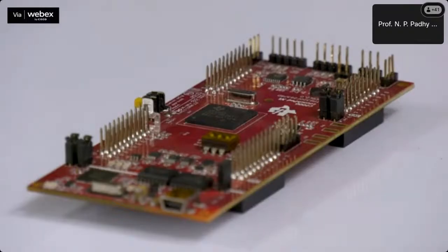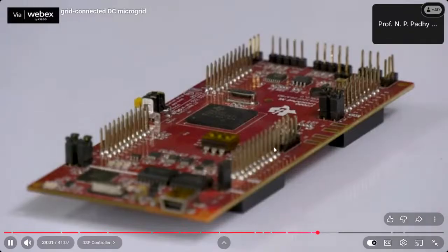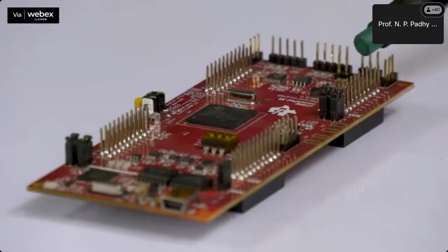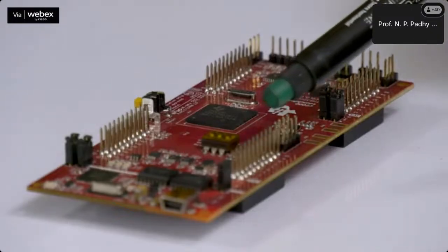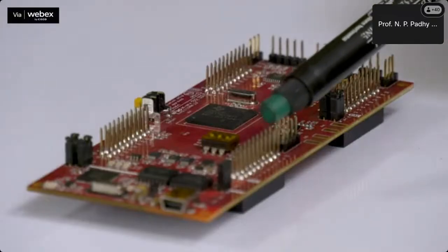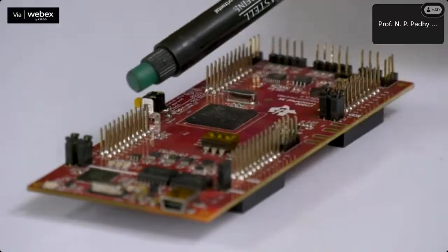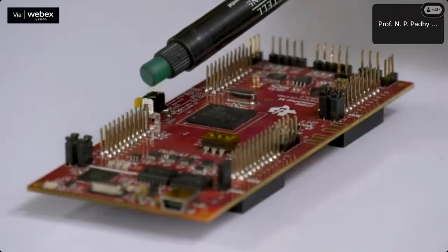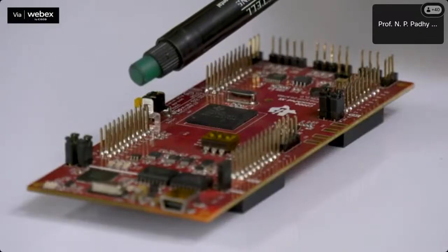The DSP controller is the most economical controller that is used for grid integration applications. For developing any rapid control prototyping, we need to configure the analog to digital converter, ADC, and PWM pins of the DSP controller. Generally, the DSP controller has 16 ADC pins of 0 to 3.3 volt input range with 12-bit resolution. It has direct 12 PWM pins for generating PWM signals at desired frequencies.